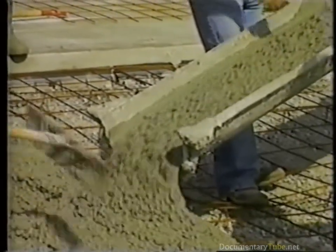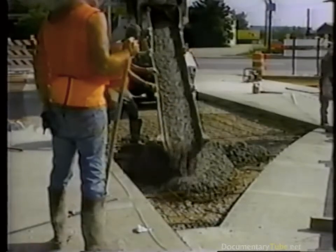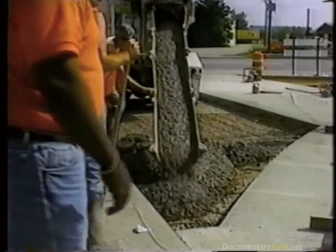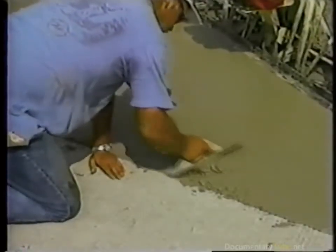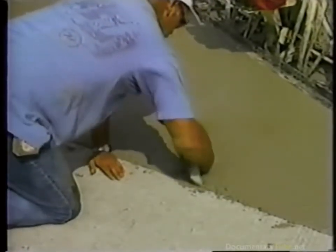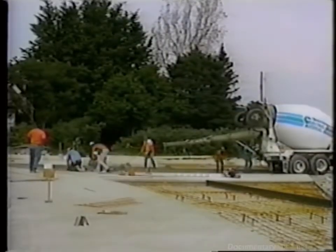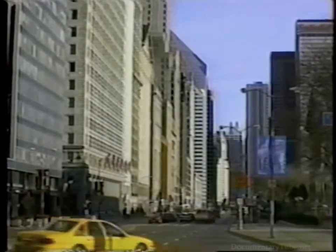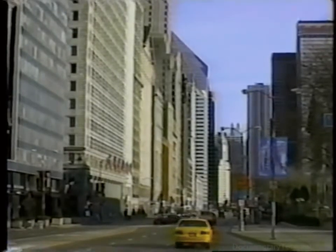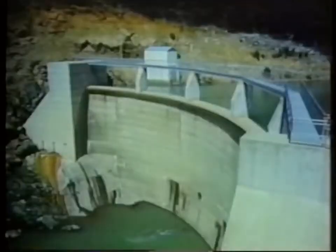In summary, hydration is a chemical reaction between the cement and water that binds the cement particles and the aggregate in concrete into a strong, enduring mass. One of the important advantages of concrete over other construction materials is that it is mixed and formed on site, and it can take on very large and flexible shapes. The ability of concrete to quickly gain strength makes it a valuable material for roads, buildings, bridges, and other important structures.